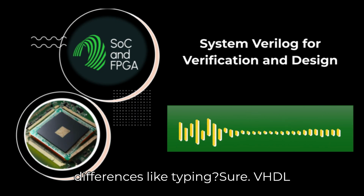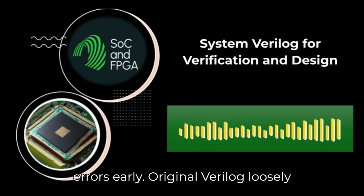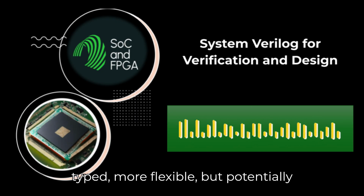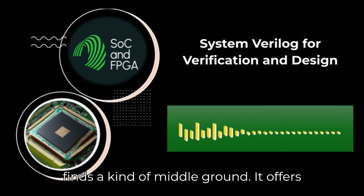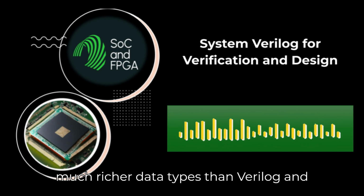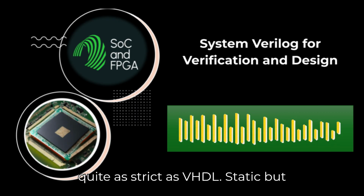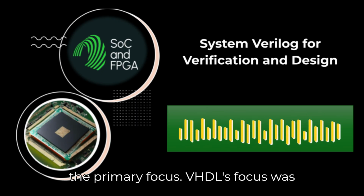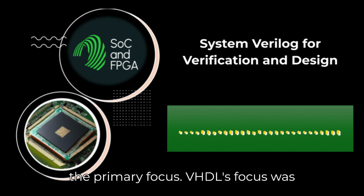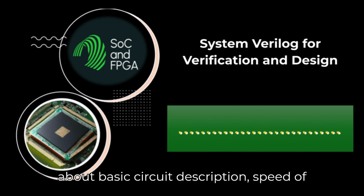Sure. VHDL, strongly typed, great for catching type errors early. Original Verilog, loosely typed, more flexible, but potentially more error-prone. SystemVerilog finds a kind of middle ground. It offers much richer data types than Verilog and stronger type checking, but maybe not quite as strict as VHDL. Static but weakly typed is the technical term. And their primary focus? VHDL's focus was really design rigor. Verilog is more about basic circuit description, speed of writing.